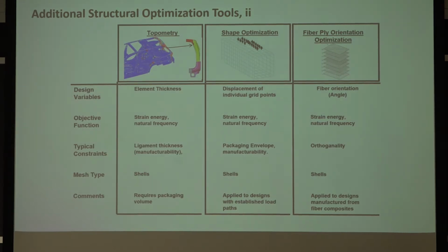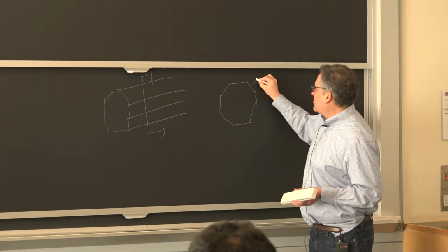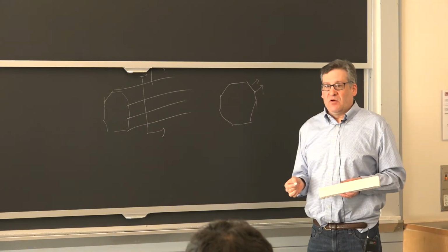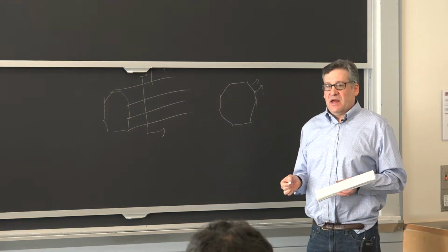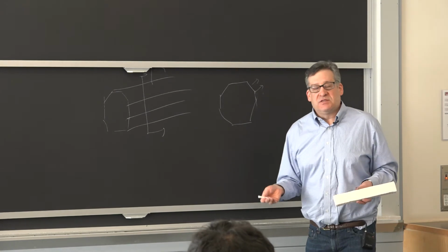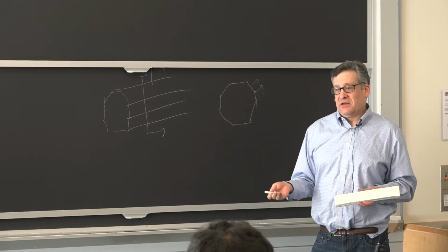Okay, let's kind of see where this is. The shock absorber mount would be right up here. The shock tower. You can think of the cross section here. And if you look at that cross section, it's very often octagonal, for reasons I can explain if you're really interested. But what shape optimization does is you put so-called perturbation vectors at the surface of this cross section, at each, for example, node in the finite element mesh. And then you have some displacement that you put in as a starting displacement, a perturbation they call it.